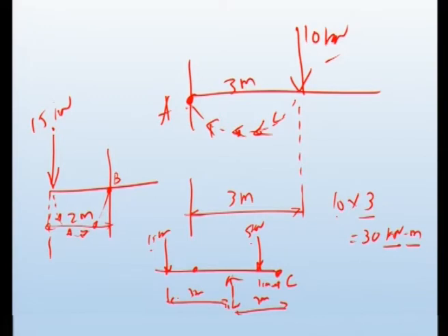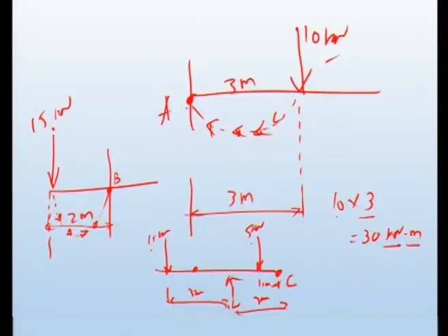So, totally we have 5 meters from C; the 15 kilonewton load acts at 5 meters from C. So, the moment produced is 15 into 5, so 75 kilonewton meter, and the nature of moment will be... simply connect this load and the point and see, and connect by means of small arrows, that will help you to decide the nature of the moment.